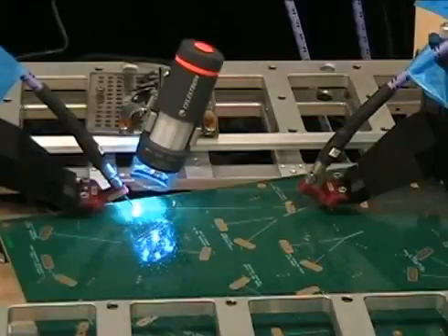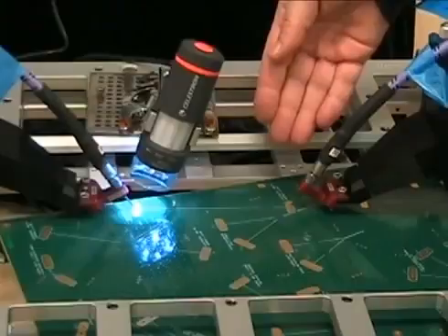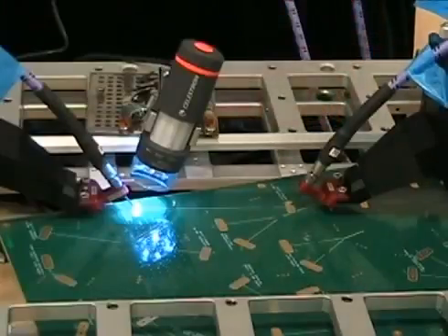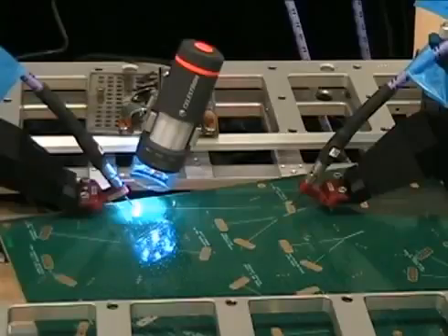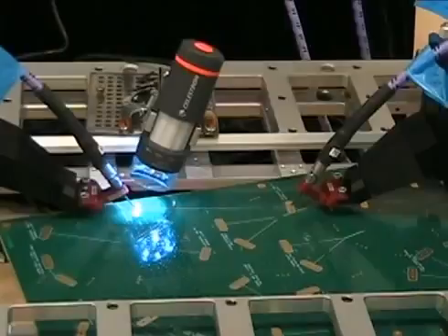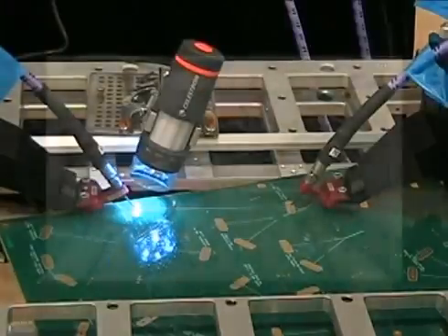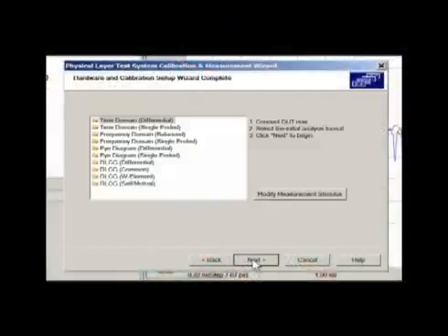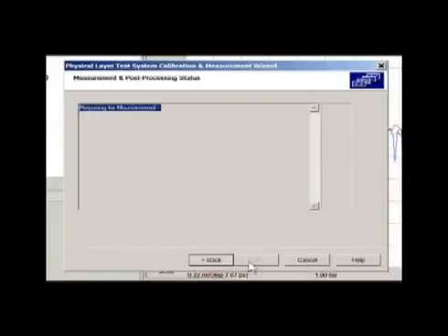Now that we have finished measuring the 2x symmetrical through and verified that the automatic fixture removal technique is working, we can now measure our actual device under test, which is simply a 50 ohm transmission line with a 25 ohm impedance discontinuity in the middle, and on either side we have the test fixture connection going to the probes. Once the connection to the dot impedance discontinuity structure has been verified, PLTS can finish controlling the VNA